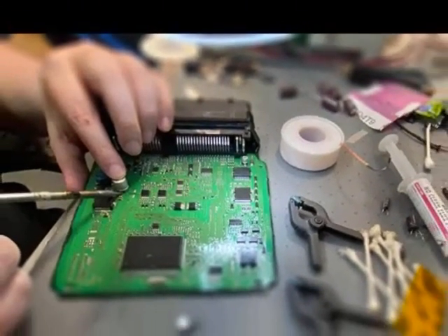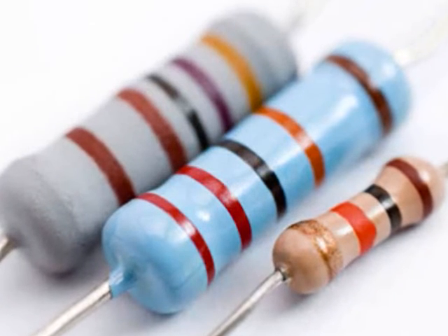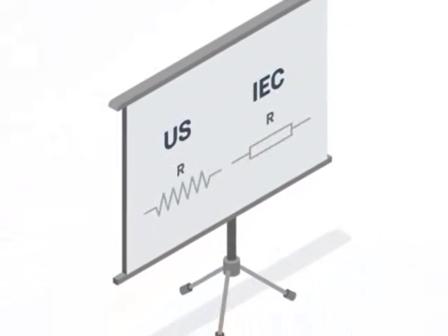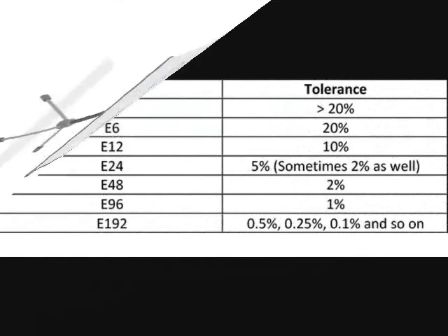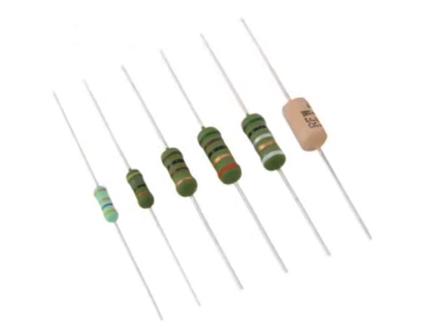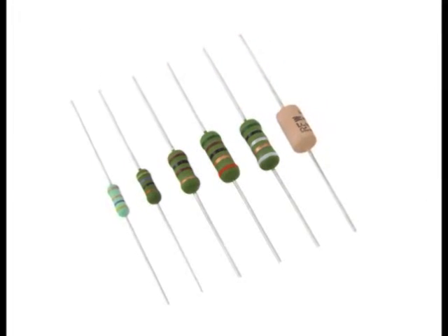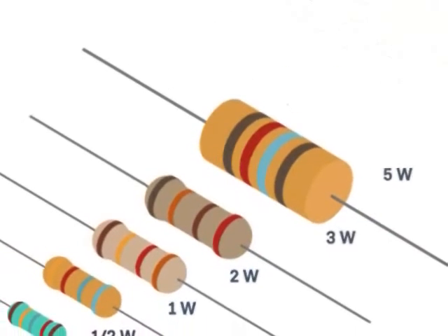The names of carbon composite resistors are written with the prefix CR, for example, CR 10 kΩ. These types of resistors are produced in the same types as E6, 20% tolerance or accuracy, E12, 10% tolerance, and E24, 5% tolerance. Their power rating is from 0.25 watt to 0.5 watt.